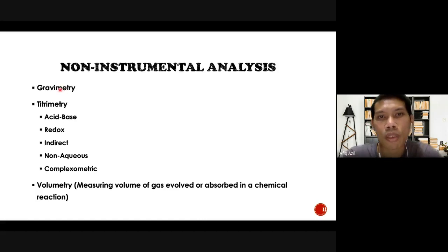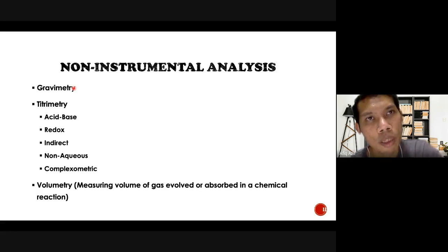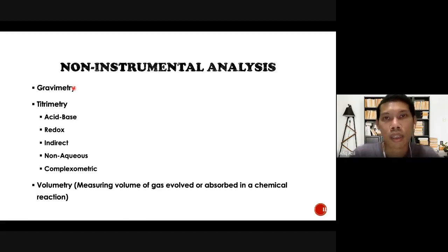The normal way is just by weighing the sample manually on an analytical balance, and then you have to heat either by using an oven or direct heat by putting it in a crucible. And after that, you have to weigh again. But by using the thermal gravimetric analysis, which is instrumental, the weighing process and the heating and the data are all collected by the instrument.